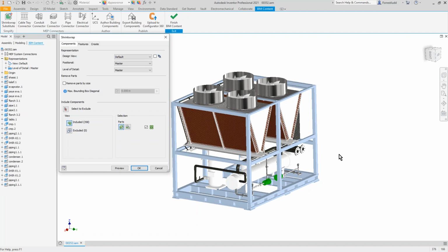The guidelines I've seen, and Inventor will even warn you about this, I believe, is if you have more than 250 components, that's probably going to make using that model in Revit painful. Now that's really an upper bound. You should shoot for as few components as possible, right? And there are various ways we can do this.